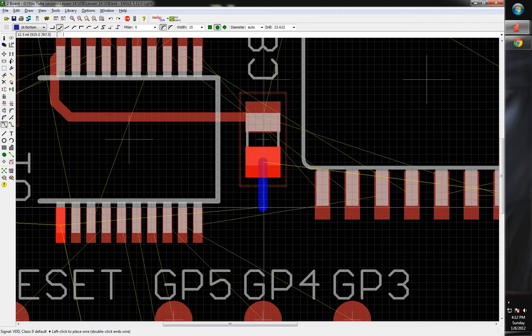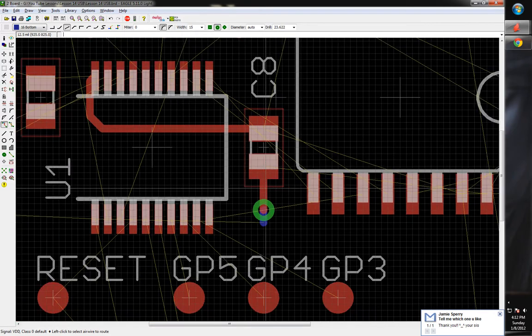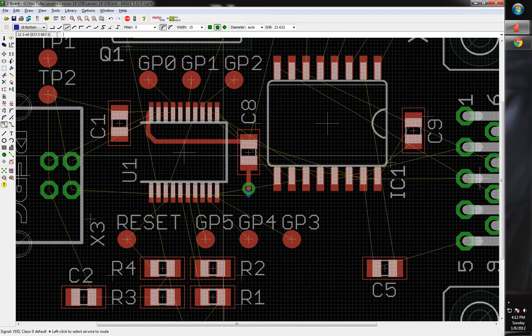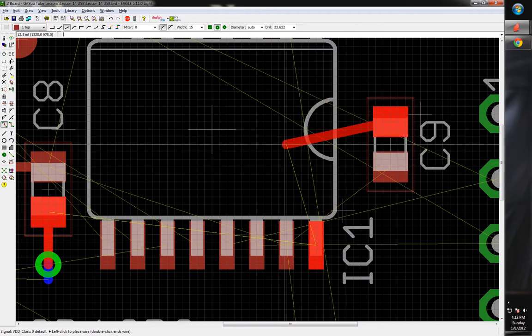I had trouble with that. Okay, we'll come out here, pop a via, come out a couple notches, and we're good. Hit escape, and that just popped a via, which just connected this to ground. So there we go. We just connected that one to ground. So let's come over here and do the same thing with this guy. Choose a miter that makes sense.